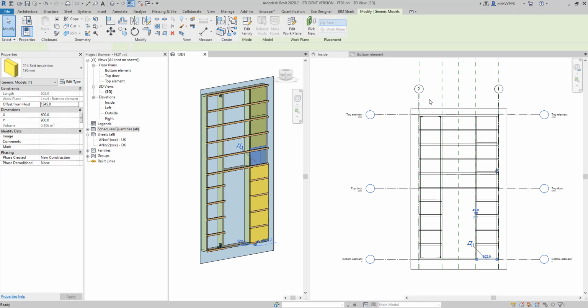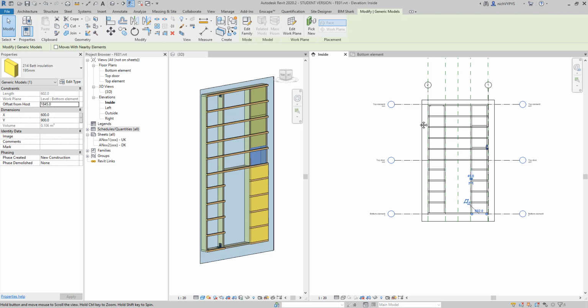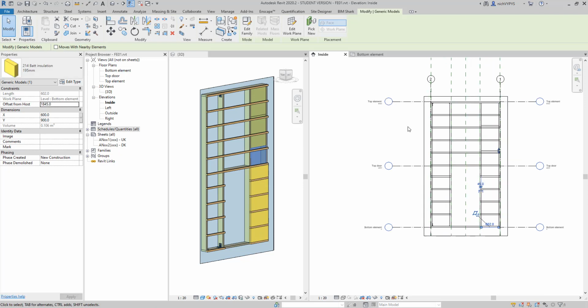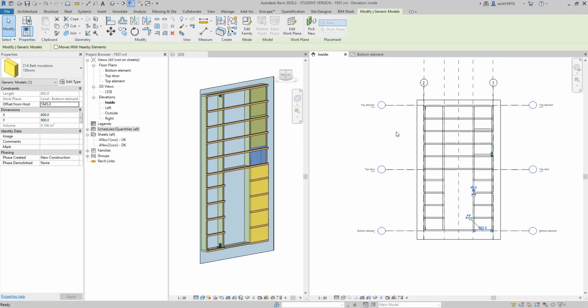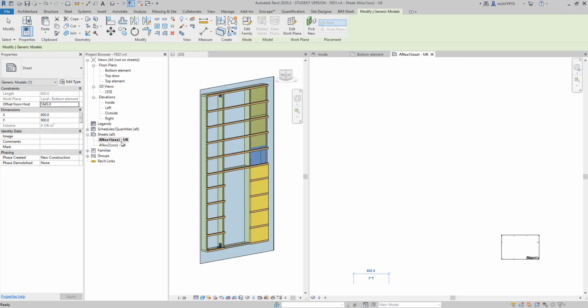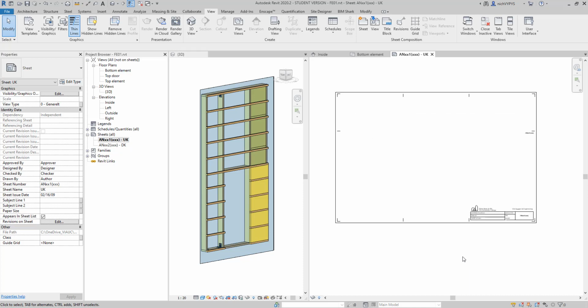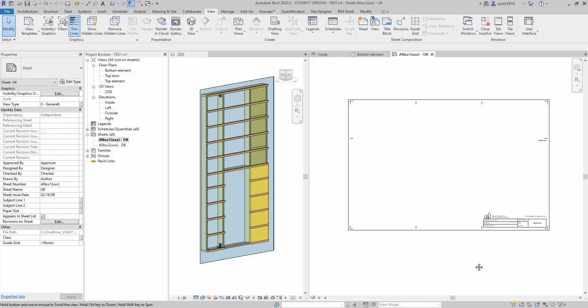So I will now focus on how to create that output drawing so that the craftsman in the production can create this element. What I'll do is take duplicates; I will copy all the different views that we have made here. I'll keep the top part of the project browser as my work in progress views.